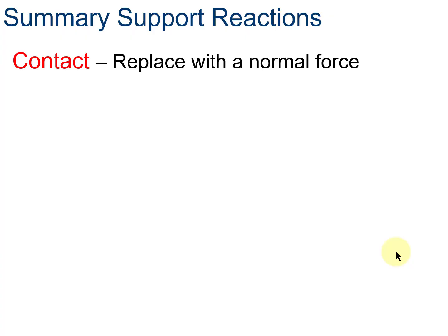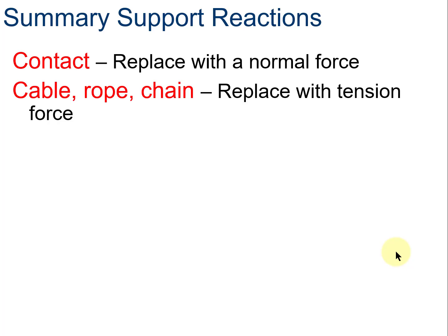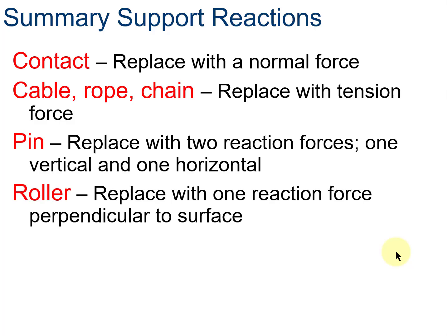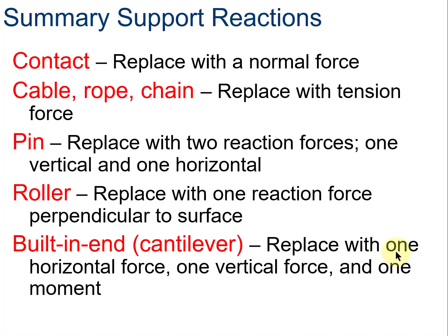Okay, summary of the support reactions. A contact is replaced with a normal force. A cable, rope, or chain is replaced with a tension force. A pin is replaced with two reaction forces, one vertical and one horizontal. A roller is replaced with one reaction force perpendicular to the surface. A built-in or cantilever support is replaced with one horizontal force, one vertical force, and one moment.